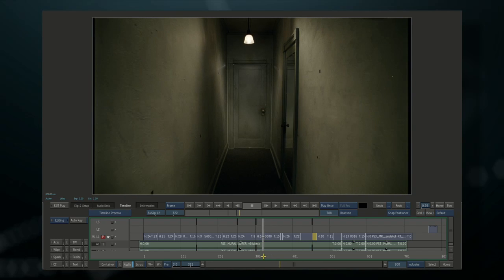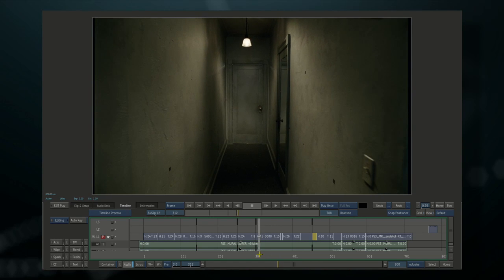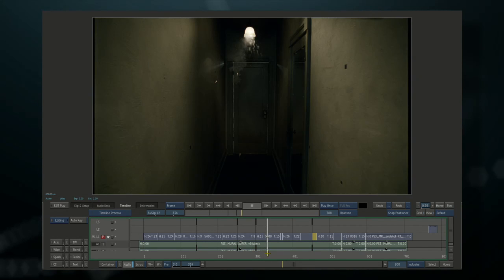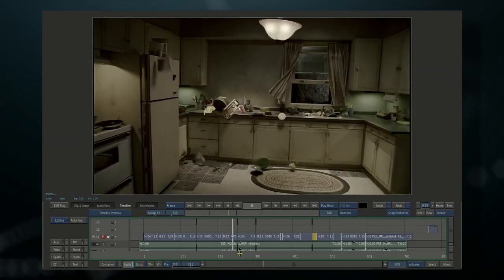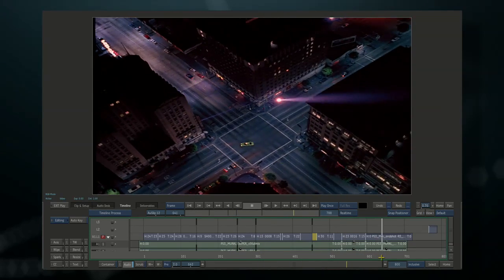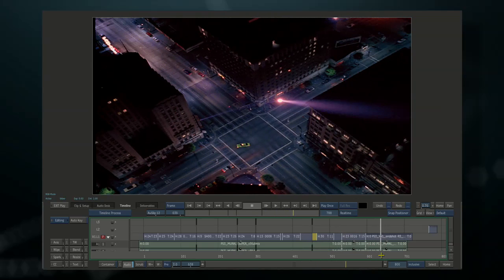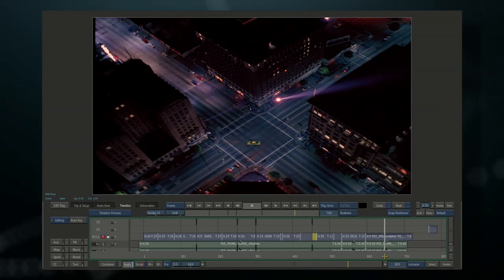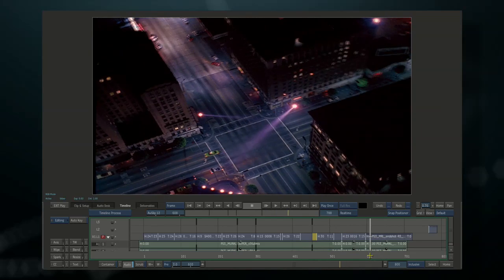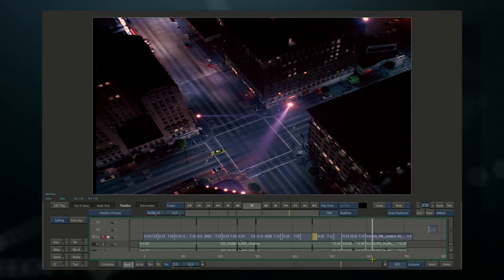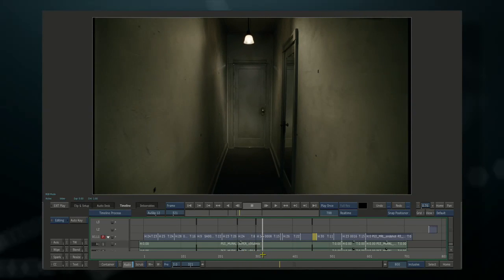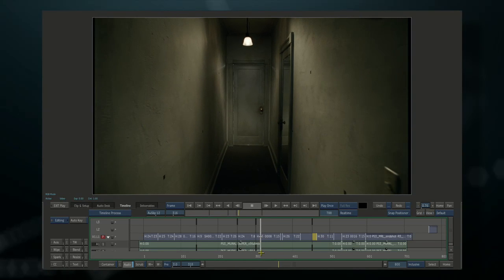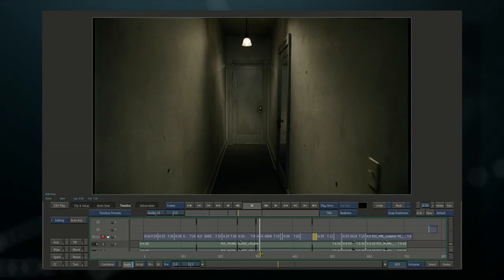Yeah, and the important thing here that I just want to mention is that we're going to use something called the film box or FBX format to distribute the assets back and forth. So it's a bi-directional process. I'll be able to take information that I gather from this end shot. Generally, I'll be calculating the original camera and then sending that camera over to Maya, and Roland will be able to place objects in front of that camera. And I'll also be able to import from Maya a 3D model representation of this wall shot to do some projections here in Flame. Yeah, you'll see a complete circle in this workflow.